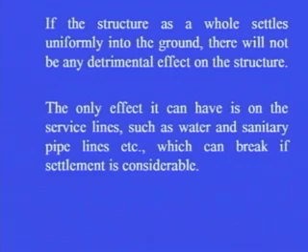Now, first of all, let us see what are the effects of settlement on the structure. If the structure as a whole settles uniformly into the ground, there will not be any detrimental effect on the structure. The only effect it can have is on the service lines such as water and sanitary pipelines, which can break if settlement is considerable.